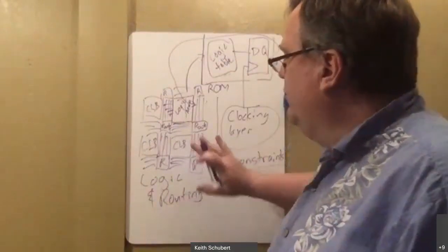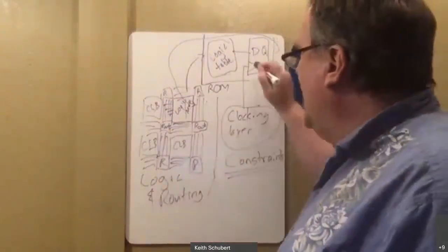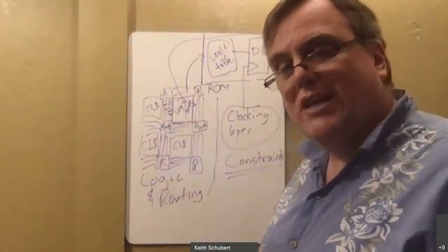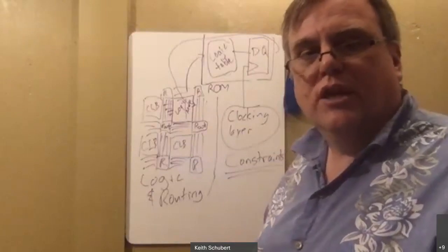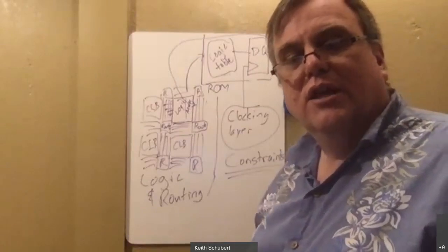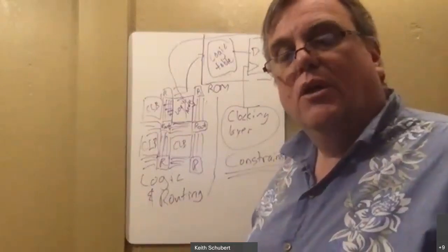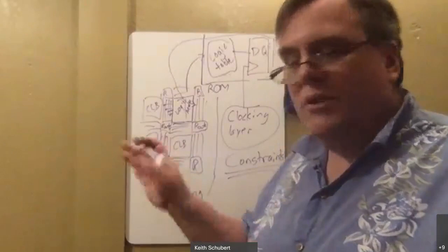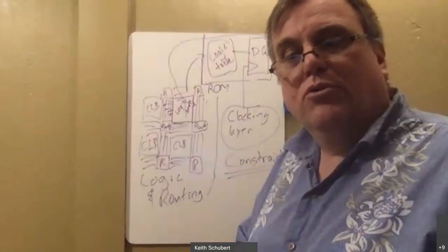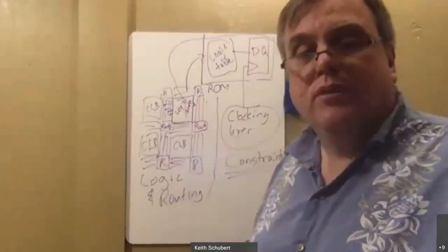So when you're doing any type of logic design on an FPGA, please do not use the clock with the logic signal. Don't use reset with the logic signal either. The resets also come in under a special case. So resets are another one of those kind of cases. So when we do that, pos edge clock, neg edge reset type of a thing, in simulation it doesn't matter, but it does matter when you go to actual build. When you go to build, those should be identified as those special signals because they go to a different layer.